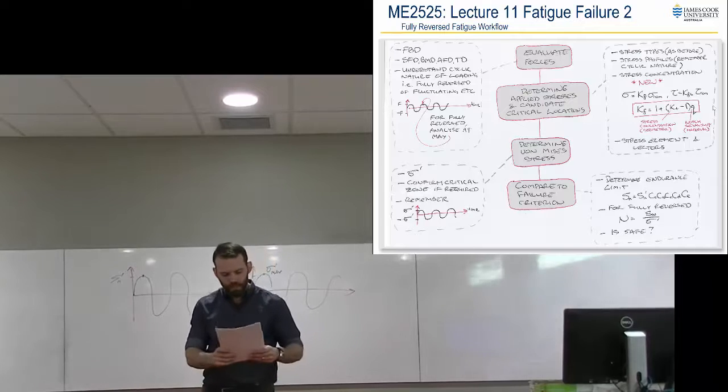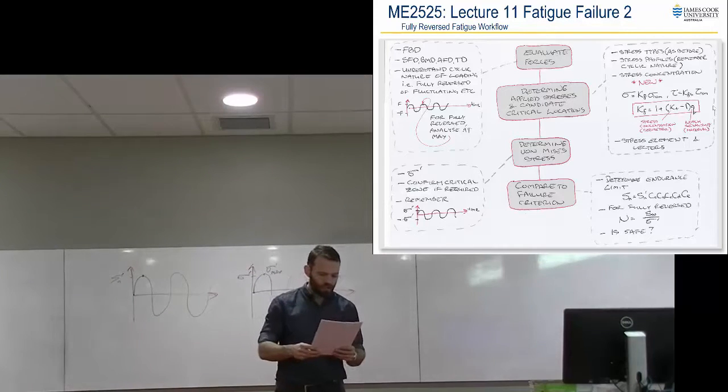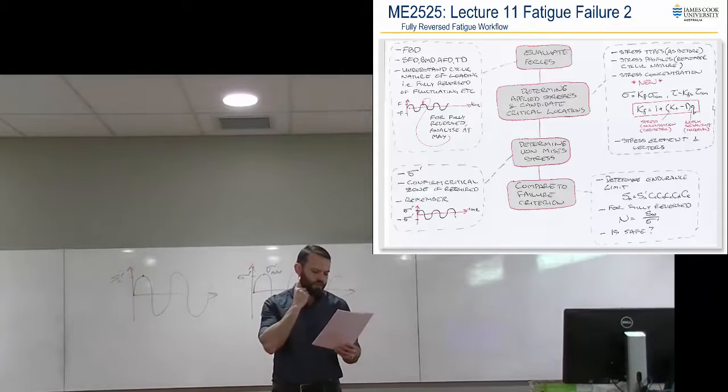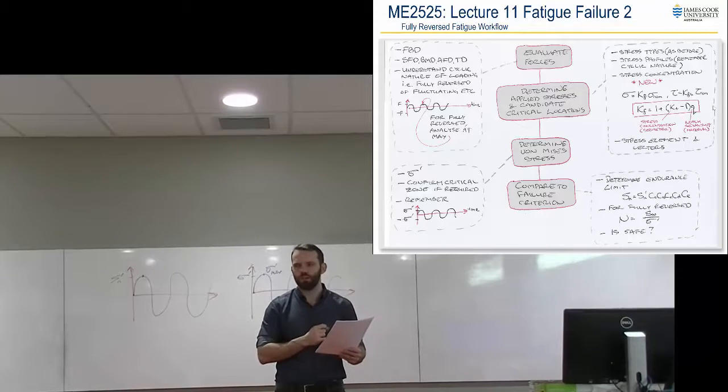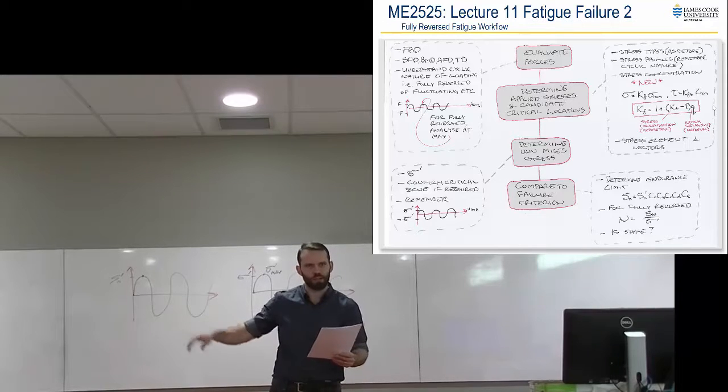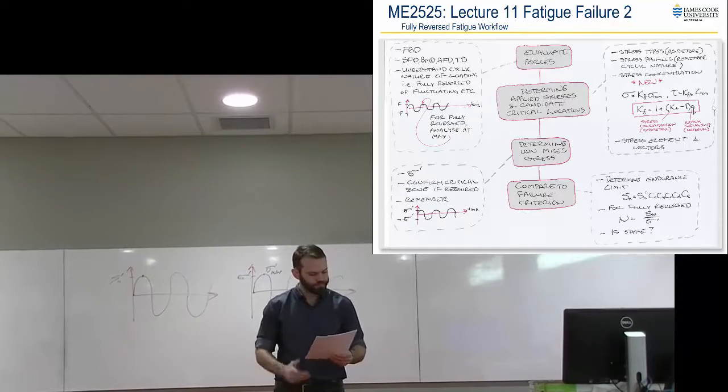Okay? Now, just to read it, look along the horizontal is notch radius. Goes from 0 to 4 millimeters in both cases. And that's millimeters, so if you have inches you'll have to convert it in this case. And look at what those lines do as you get to 4. If I had a notch radius of 10, what do you think the values would be? Pretty much whatever the values on the right hand edge are, yeah? They look like they effectively plateau out to constant.